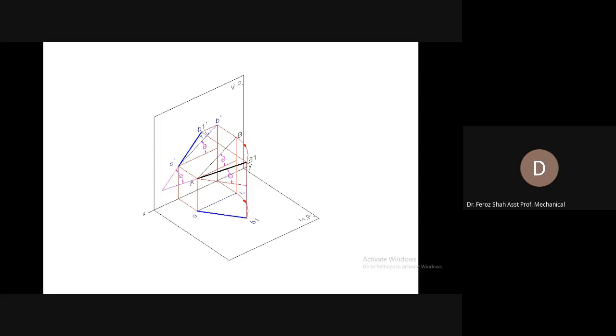By drawing a new front view, you can see that B has been rotated to this position and is given the name B1. Now, projecting B1 onto the vertical plane with a projector perpendicular to the plane of projection, and similarly A would again be projected to the same position because we haven't moved A, and B1 will be projected to this position on the vertical plane.